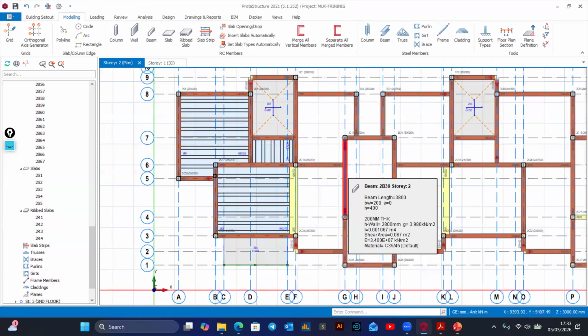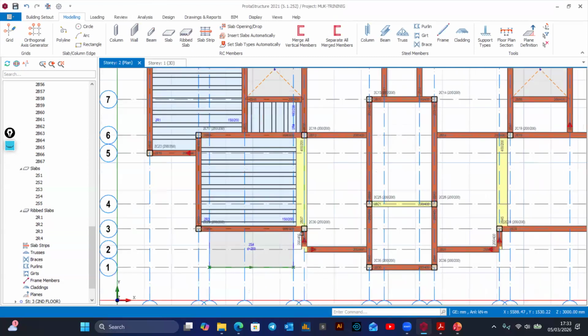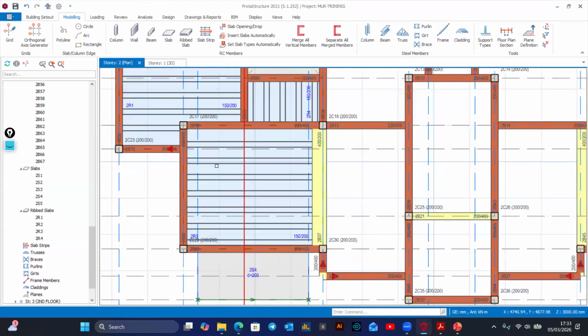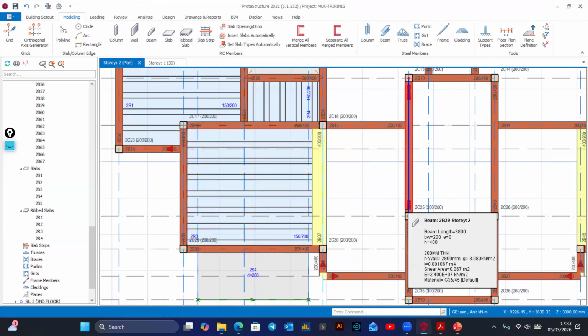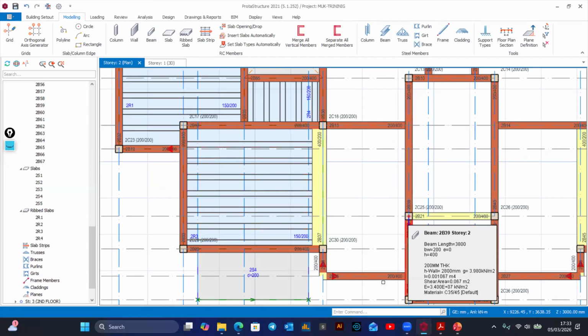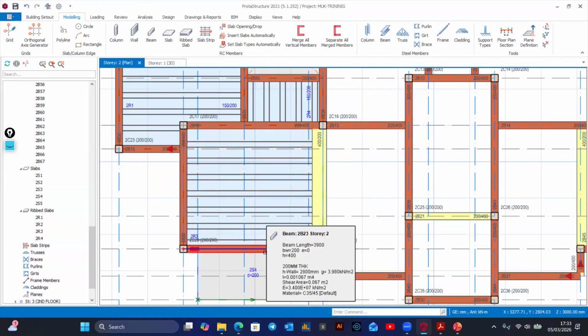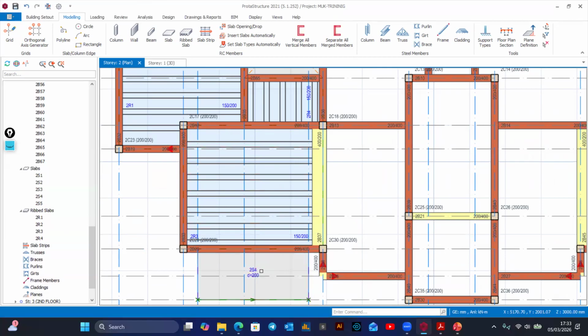Likewise here, now, actually, this is very good. When you look at this area here, if I have ribs spanning like this, that means that this beam is only carrying weight of the slab, the cantilever. It's not receiving a load from the ribs.